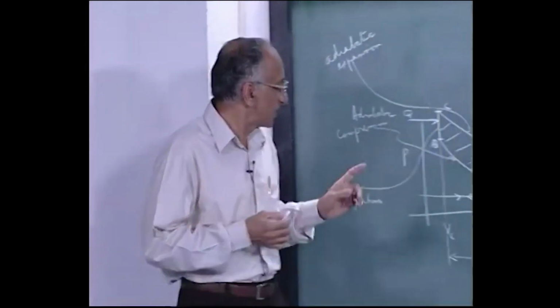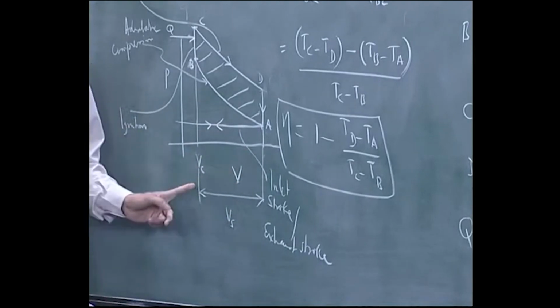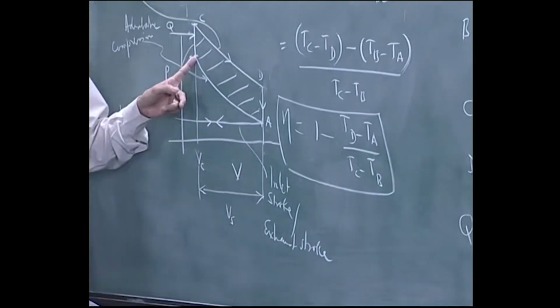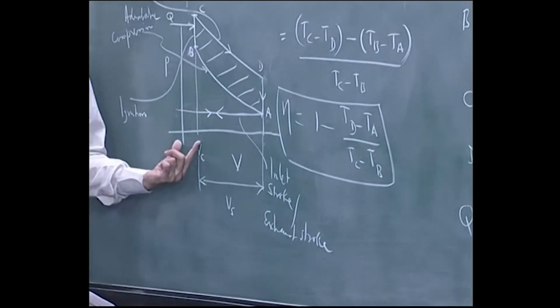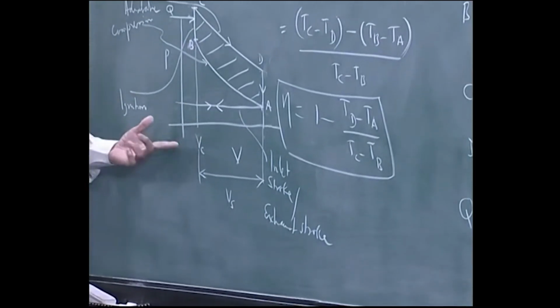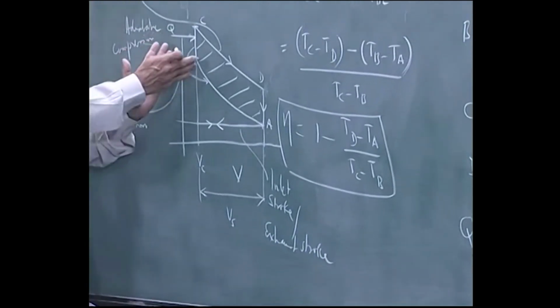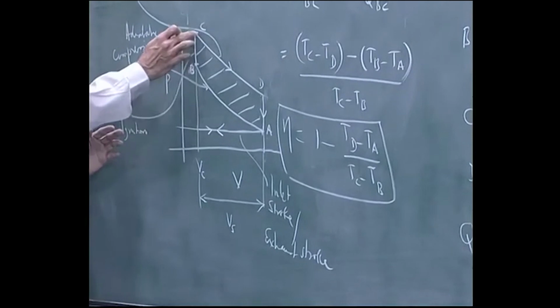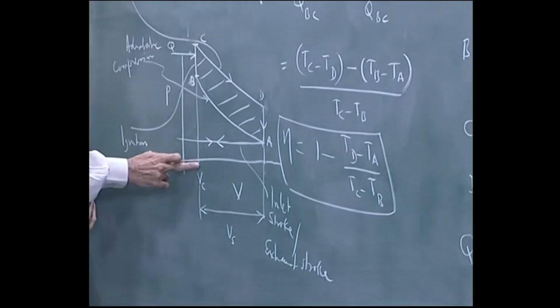And the compression ratio also determines the pressure from here to here. Depending on this ratio you get higher or lower pressures. And if you look at this clearance volume, it has physically a bad influence, because at the end of the process when you compress it, you have clearance, you have gases at the end of this process at this pressure and at this volume.